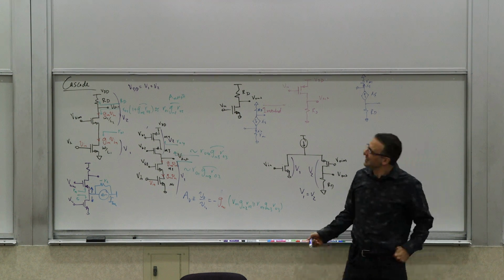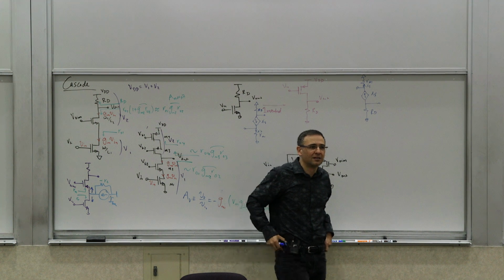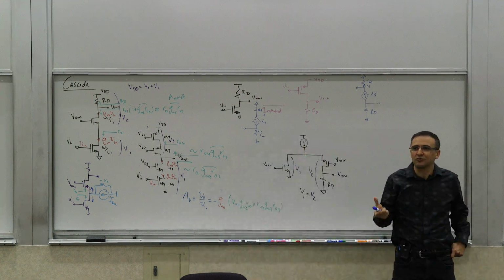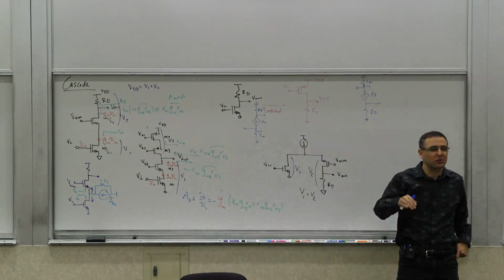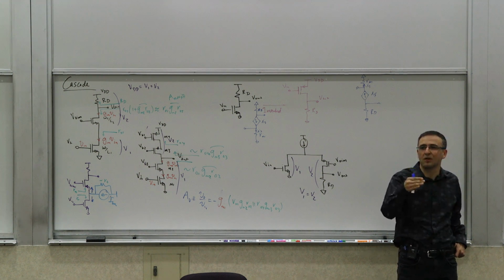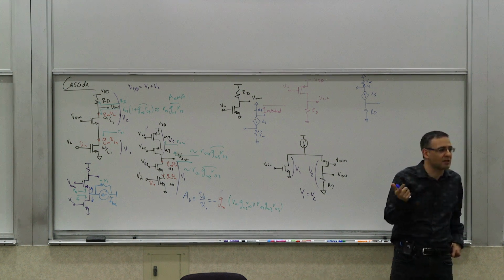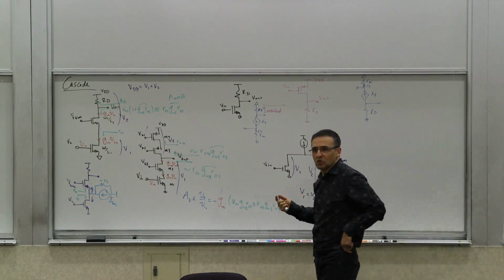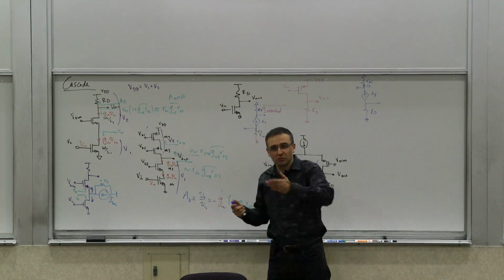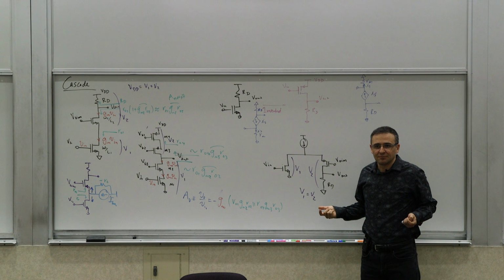Well, the current is going to be the same, right? Because you're passing the same current through the same thing. It's a headroom issue again. It can't go too low, it stops being a current source. Basically, it leaves the pinch-off region earlier. So the range of actual operation, the usefulness of it, is reduced. But going back to your question, which is a good question, is that not necessarily.